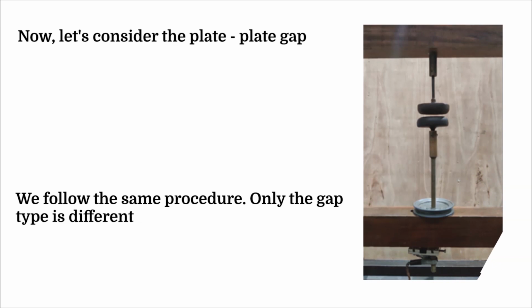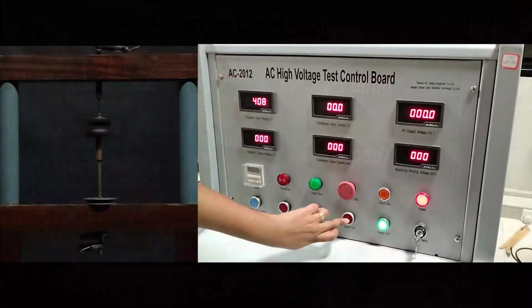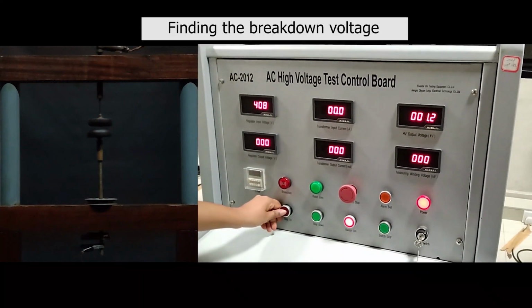We follow the same procedure, but now we use plate-to-plate gaps. Let's consider the gap length of 1 centimeter. We increase the voltage as in the previous instances, and note down the voltage at which breakdown occurs.